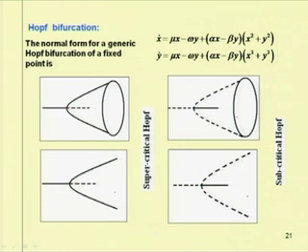But if from an unstable trivial branch it becomes unstable again, or from a stable trivial branch the periodic response becomes unstable, so the resulting response becomes unstable, then this becomes a subcritical Hopf bifurcation point.